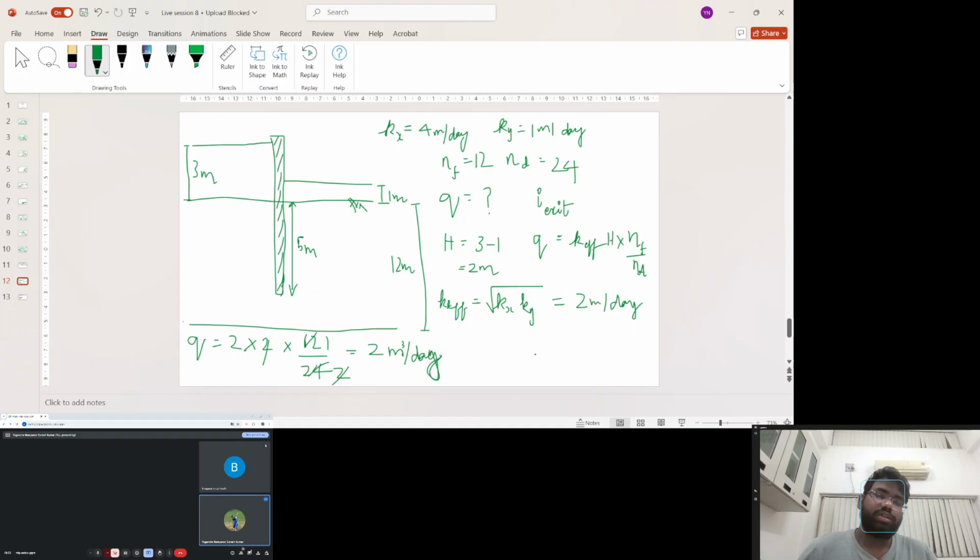So this is the discharge that takes place. Now coming to the exit gradient. So I exit, which is determined as IE, which is equal to delta small h, the head drop within one flow grid, by the length of the flow channel. The length of the flow channel is given to us as the average length, so that can be taken as the length of the exit flow also.